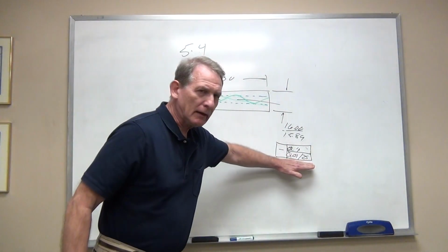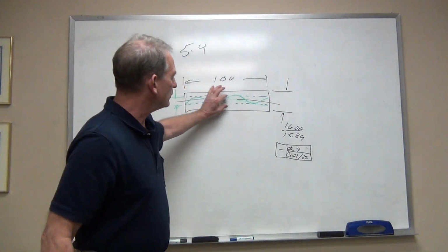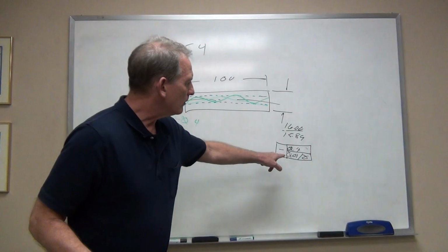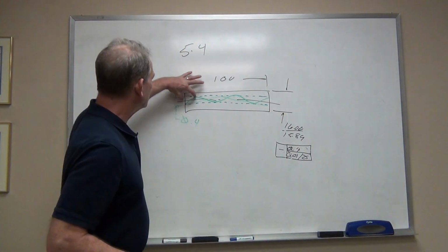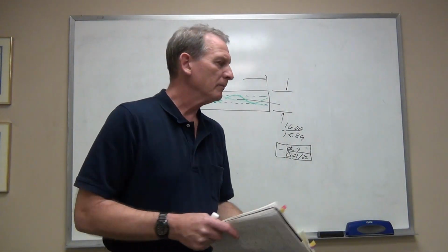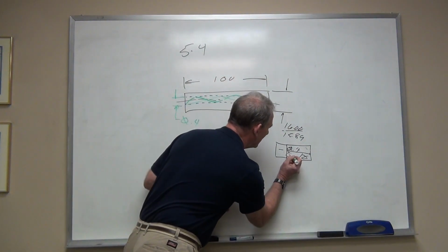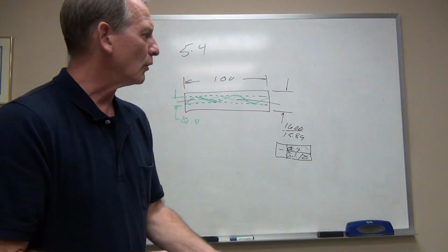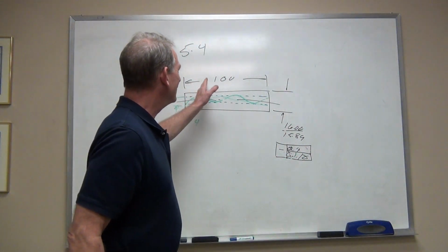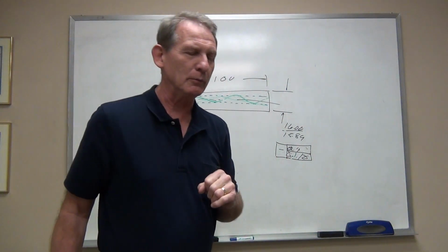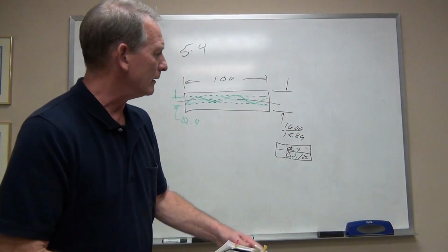So he has added basically a modifier to the tolerance zone, saying that yes, you can have a total of 400 thousandths tolerance zone over the length of the shaft, but in any given 25 millimeters over this 100 millimeter length, the total amount of lack of straightness can only be 0.1.